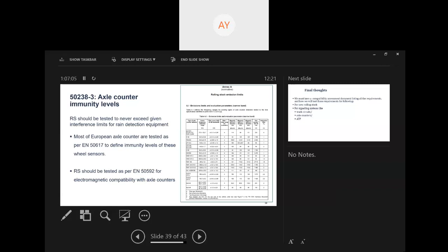And then their center frequency and their filter curve, and then the magnetic field in X, Y, and Z directions for each of the sensors, the limits of magnetic field which should not be crossed by an external influencing component or device. And also the rail current in that specified frequency is given, which should not go beyond that limit.